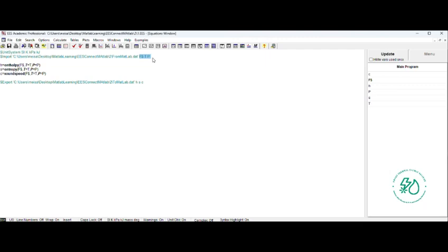The values from the dat file are assigned to the variables, then the required operation is done inside of the EES file. And finally, by $export directive, data from EES is exported to the external dat file, called here to matlab.dat. But just the variables that are mentioned here at the end of the line. As we can see here, we have H, S, and C.